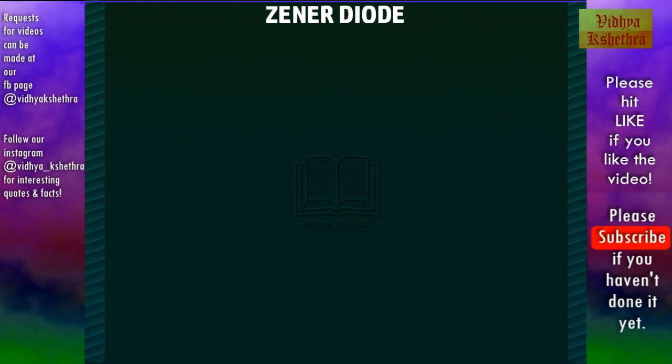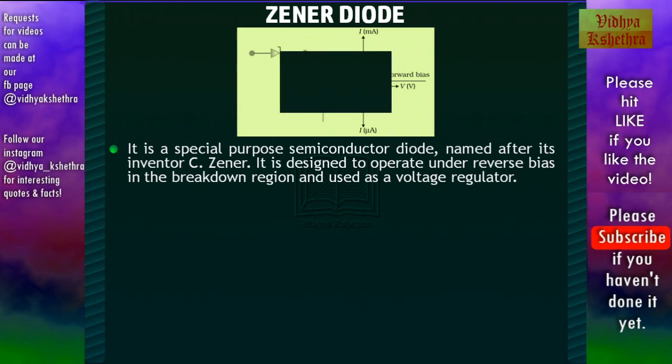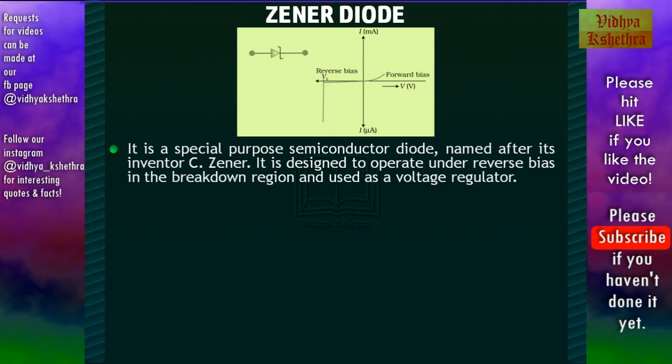Now we can see about special types of diodes, and the first one is the Zener diode. It is a special purpose semiconductor diode named after its inventor C. Zener. It is designed to operate under reverse bias in the breakdown region and is used as a voltage regulator. This figure shows the symbol of a Zener diode as well as its voltage and current characteristics.